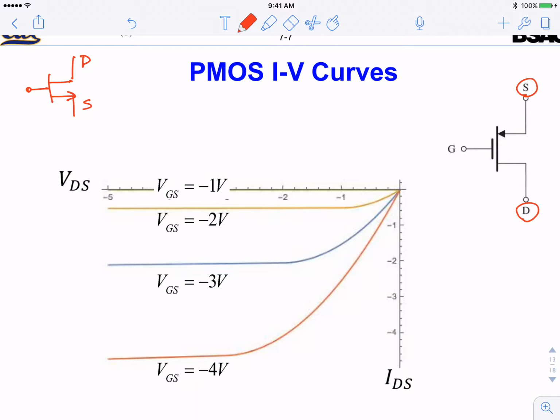Okay. And how do you remember this? Well, you can think of CMOS. CMOS consists of basically PMOS on top, NMOS at the bottom. So this is a CMOS inverter. Okay, so you have PMOS usually on top, NMOS at the bottom, and on top the source is also on top. The current follows exactly the arrows in this case. So current flows in this direction.